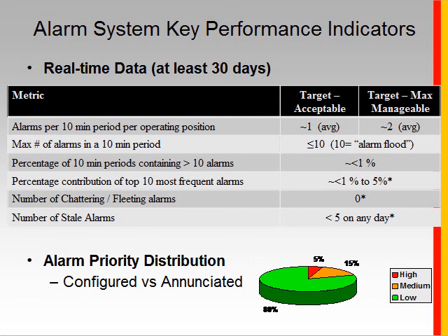We think about the Milford Haven incident where the operators got 275 alarms in 11 minutes, significantly more than what the standard would call for, and you can see how that would be just totally unmanageable. Now, there are going to be times when you do have planned upsets and you're going to have a lot of alarms generated. If you've got more than 10 alarms in a 10-minute time period, that is considered an alarm flood.